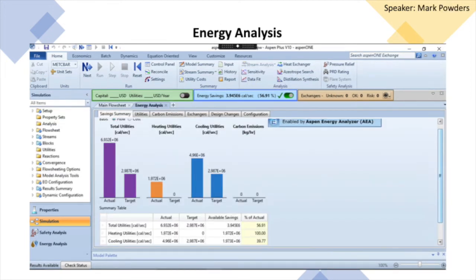Energy consumption and generation was evaluated using the energy analysis function, which is useful to identify potential energy savings. To save energy, several design choices were made. For example, the first MTO distillation column split, between ethane as the light key and propylene as the heavy key, was easy due to a high boiling point difference and relative volatility between keys.